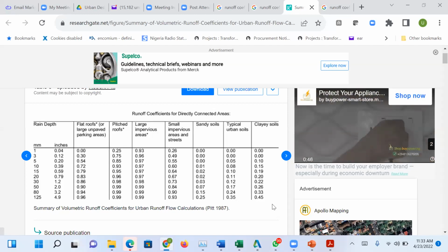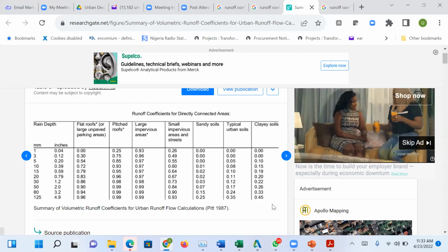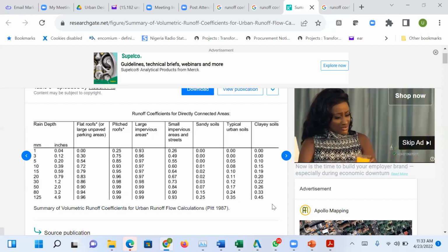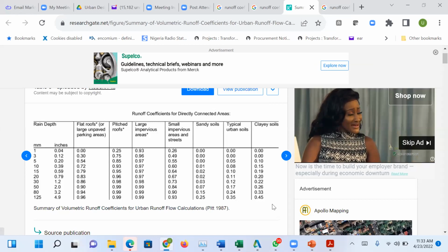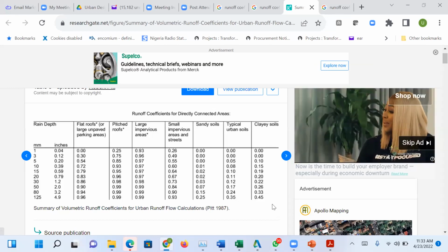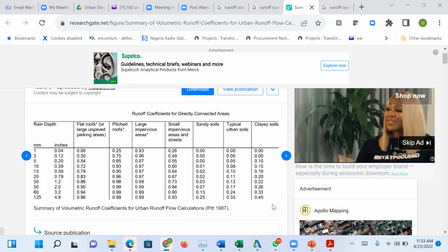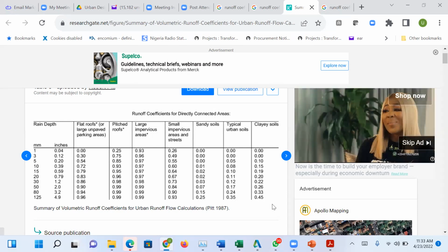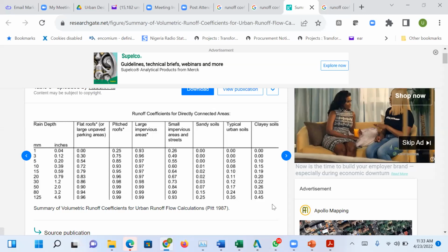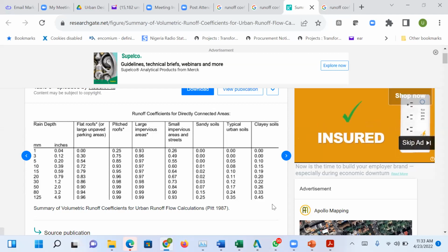It comes with intensity, it comes with speed, and if the place happens to have a high slope, then it will come with a supercritical flow. And when it comes to this particular flow, what does it do? It will erode the underlying surface because it has a lot of energy. And if the Manning's n of that surface is low, then it will just carry everything.